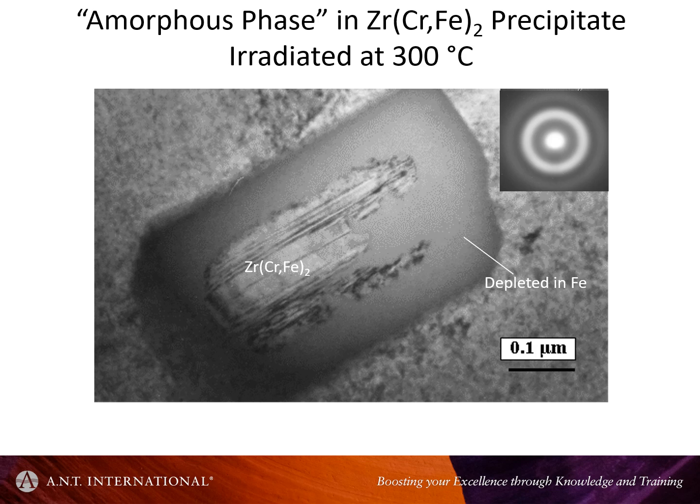So iron dispersal from any component, whether it's as a phase, a compound, or as an impurity, typically the rule of thumb is, when you irradiate any material with iron in it, the iron just gets spread everywhere. So this iron was diffusing out, and the way I interpreted this was the decrease in the stoichiometry, because ZrCr2 is essentially a highly stoichiometric material. The decrease in the stoichiometry by the iron departing meant that this material then became amorphous.